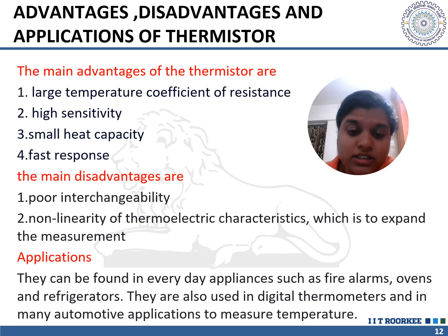The main disadvantages are poor interchangeability and non-linearity of thermoelectric characteristics, which limits the measurement. And now applications. You might be aware of many of them, but I'm still mentioning them, and you can refer to some of the applications which you don't know. They can be found in everyday appliances such as fire alarms, ovens, and refrigerators. They are also used in digital thermometers and in many automotive applications to measure temperature.